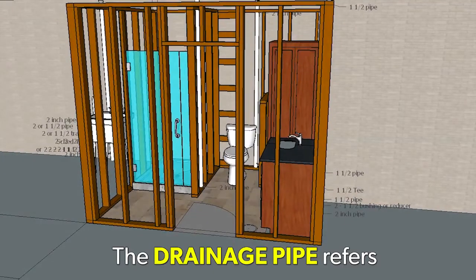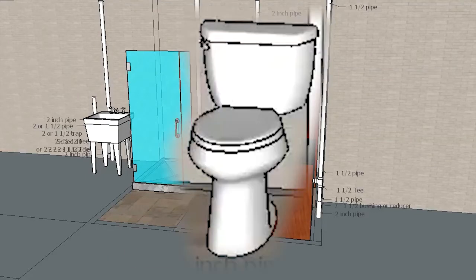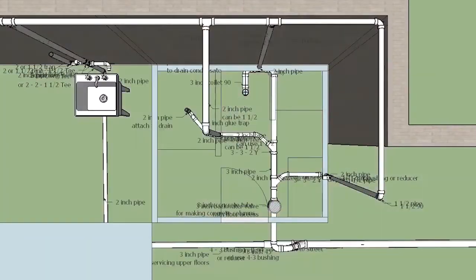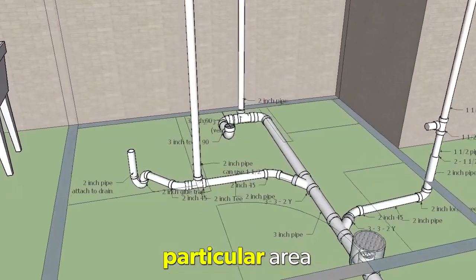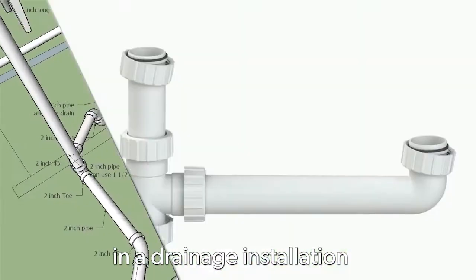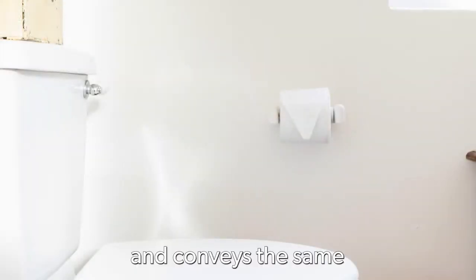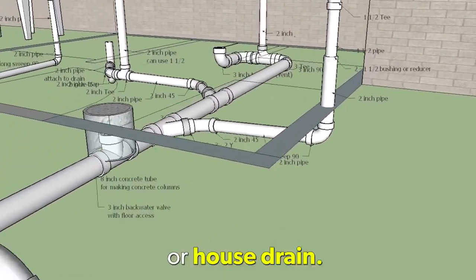The drainage pipe refers to an installation that receives and conveys discharges from water closet with or without waste coming from other fixtures, and in simpler terms, a pipe responsible for removal of water in a particular area. On the other hand, the waste pipe is any pipe in a drainage installation that receives the discharges of any fixture except water closet and conveys the same to the soil branch, soil pipe, or house drain.